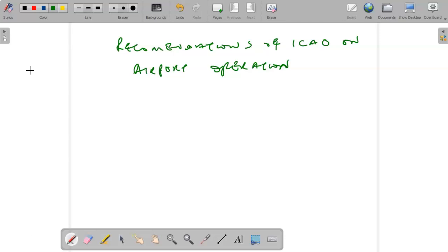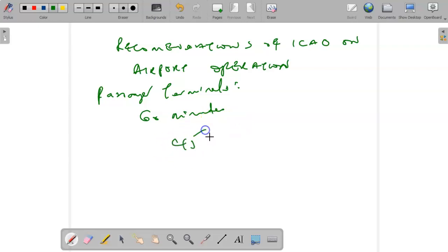States have further criteria and standards specific to the characteristics of national airport operation. For passenger terminals, ICAO recommends the following practices: 60 minutes for international departure passenger processing, from presentation at the first processing point to the scheduled time of the flight, and then 45 minutes for international arrival passenger processing, from embarkation or disembarkation to completion of the last clearance process.